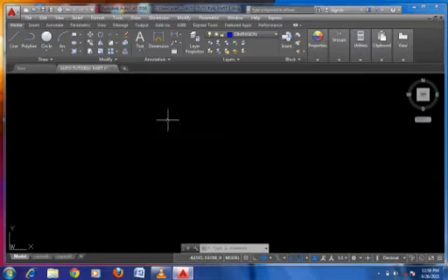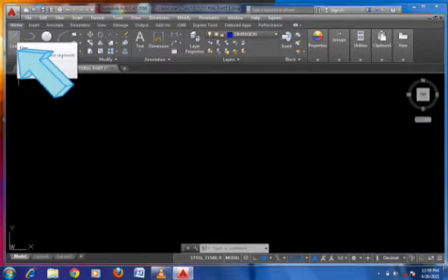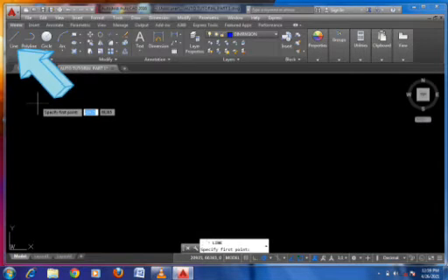So now in this my AutoCAD tutorial video part 1, I will model the external wall of our simple floor plan that I will be modeling in part 2, so that I will guide us through there. We can know some basic tools and how they function on AutoCAD. So let's start with the modeling of the external wall of our simple floor plan. I'll be modeling it in 3 ways. And the first way, I'll be using the line tool. And you click on the line tool here.